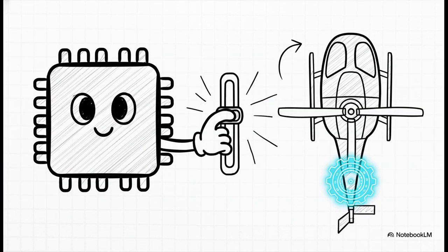And here's the real magic. The system doesn't need to be pre-programmed with some perfect zero torque value. The yaw control loop finds it all by itself. Its only job is to keep the nose straight, and the only way it can do that is by applying the exact amount of power needed to cancel out the motor's drag. It effectively creates a perfect virtual freewheel, just as a side effect of doing its main job.